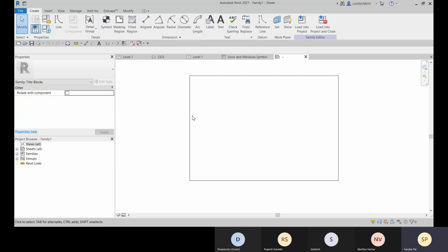It will be half of your A0, the previous paper size, the half of the bigger length of that previous paper size, that is A0, half of 1189, that is 594 into 841. 841 will be as it is.